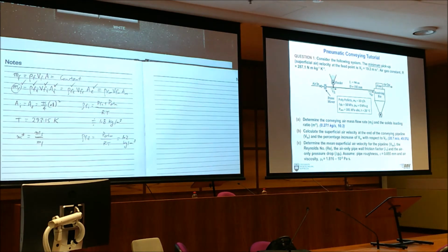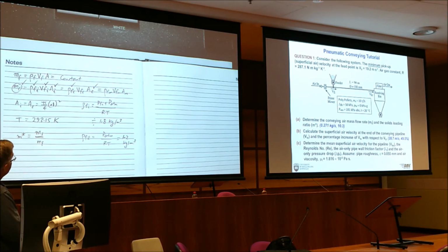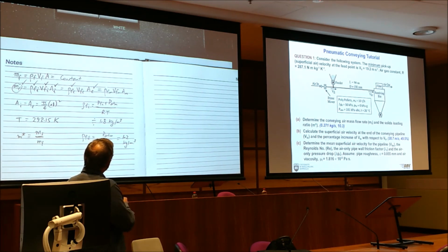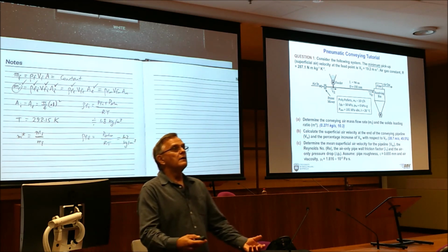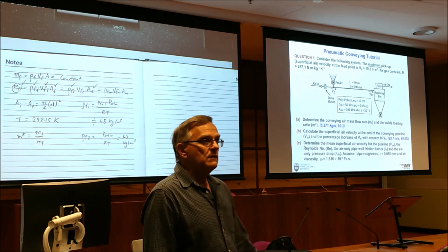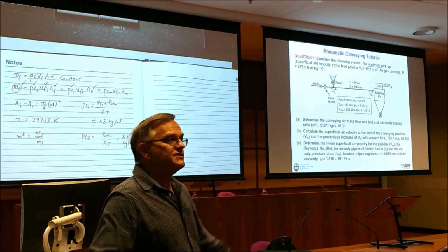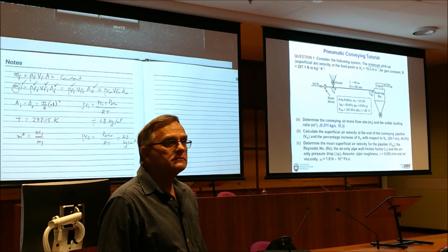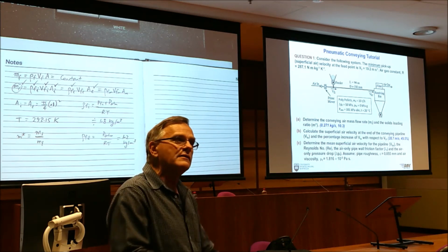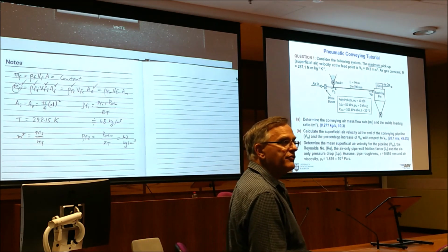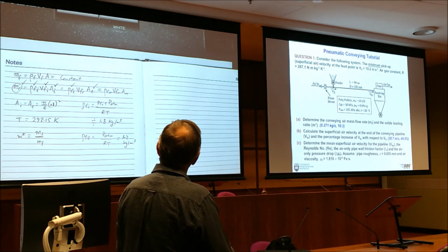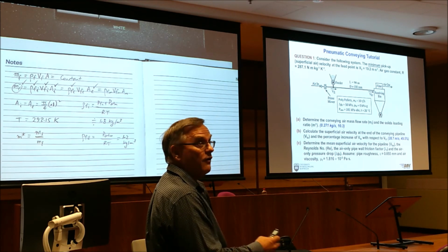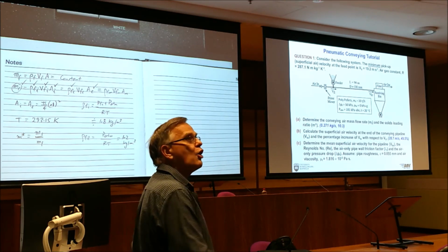AM is the same as AI and AE. Okay? So rho FM, VFM equals rho FE, VFE equals rho FI, VFI. So what's rho FM? It is the mean gas density. Inlet is 1.8, exit is 1.2. What's the average? 1.5. You can do it a bit more accurately on the calculator, right? But just the process you go through: you take the average of rho FI and rho FE, the arithmetic average. That's fine. Then you use continuity to work out the corresponding mean gas density.